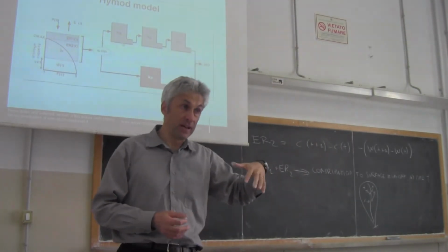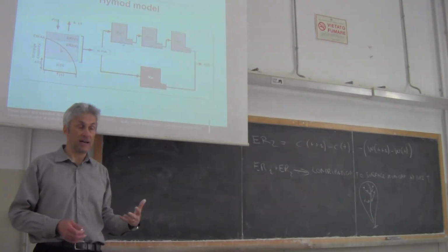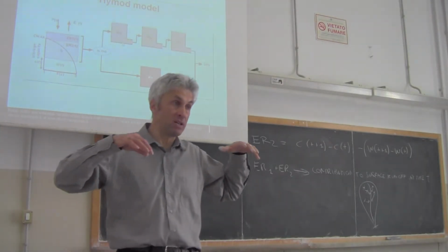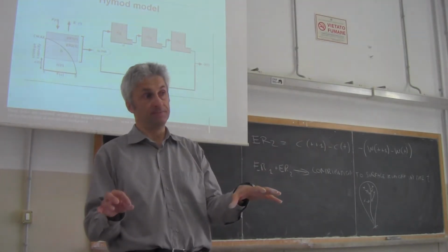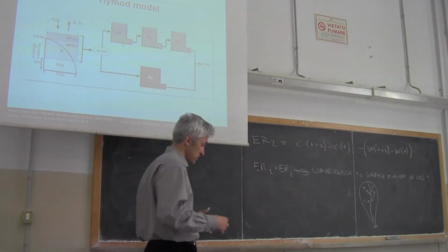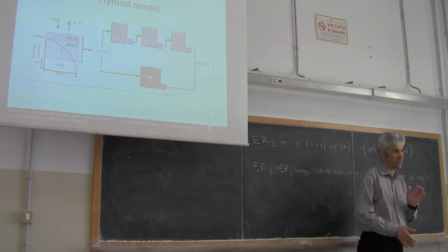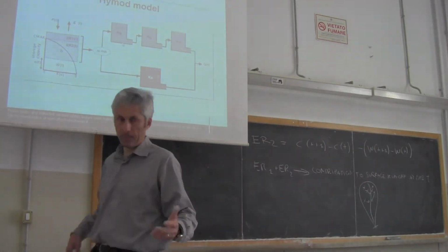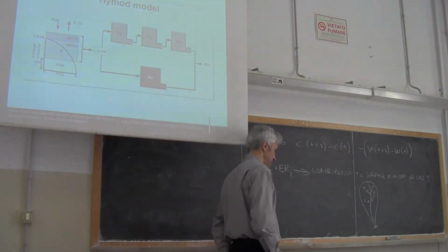The other component is a slow response, like the trip that the water drops may take by infiltrating into the catchment and flowing in the underground. So there are two possible trips from each individual location of the catchment to the closure. One fast way and one slow way.